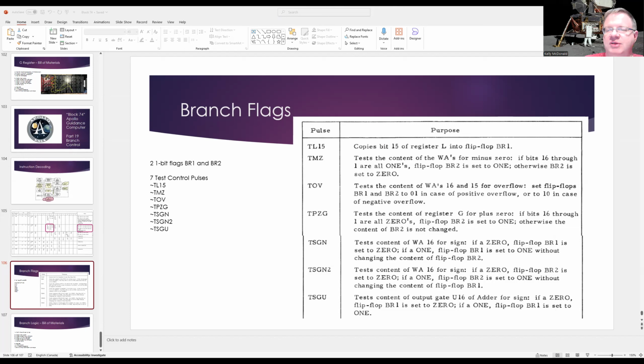So we have this little AND here so that even if we pulse the clock, we're not going to pulse BR1 in this particular circumstance. We'll just leave whatever data is in that D latch. All of that builds our logic in order to set these two bits.